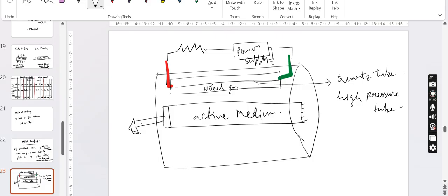Initial boosting of this applied voltage through some electrical manipulation is a prerequisite, as discharge impedance at a high gas pressure is too large initially for just the power supply voltage to take over. Because of the non-ohmic nature of the impedance of the gaseous discharge, the real resistance R is usually connected in series to stabilize the discharge.